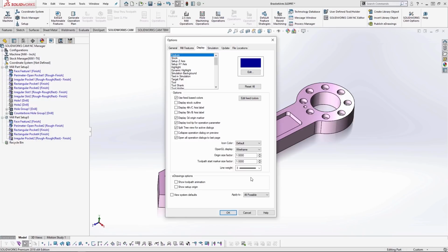The display area controls how I'm interacting and how I'm viewing or seeing the SOLIDWORKS CAM UI. One thing that SOLIDWORKS CAM does that CAMWorks doesn't is it creates different colored toolpaths for every type of toolpath. So center drills tend to come in differently than, say, rough mills, which look different than contour mills.